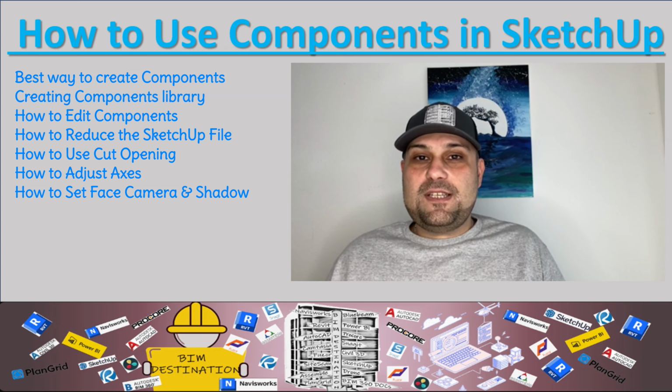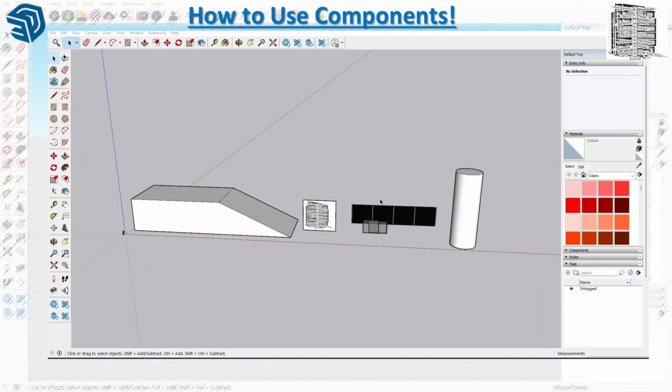In today's video, I want to review the difference between a component and a group, and also go into a component in detail and understand how we can leverage this great tool that we have in SketchUp. So the main difference between the component and the group: a component stays in your model and is saved in your component library.